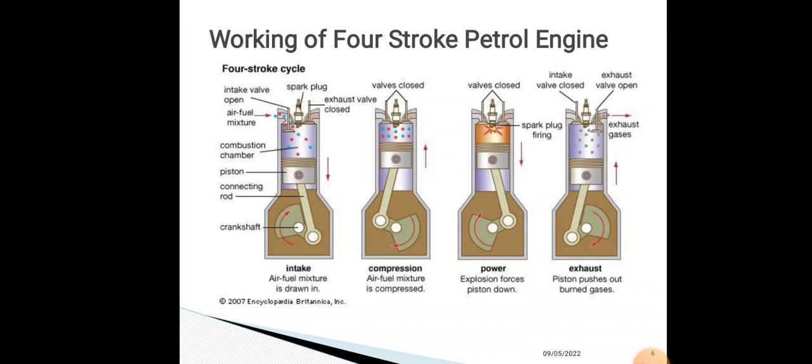In the expansion stroke, the high pressure of the burned gases forces the piston towards the BDC. Both the valves are in the closed position for the power stroke. During this stroke, power is produced, and both pressure and temperature decrease during expansion.